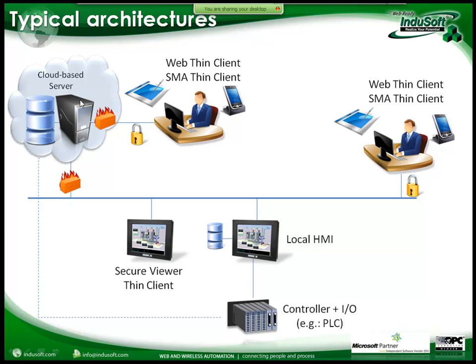And using the built-in security system from InduSoft Web Studio, you can filter the information available to each remote thin client, to each remote user with a web browser, based on the username and password. So you could have a group of users that have access to one site or a set of sites, and another group of users that have access to the information from other sites, and so on and so forth.